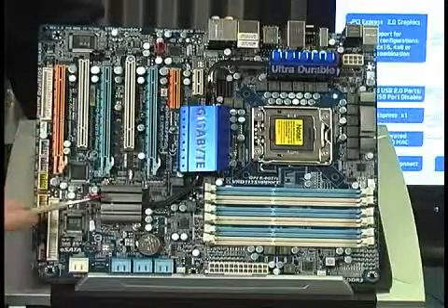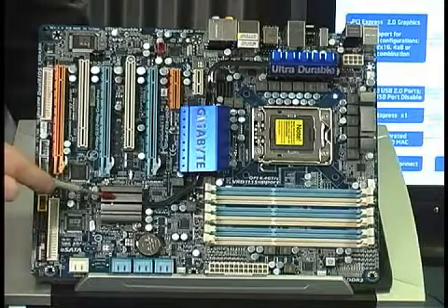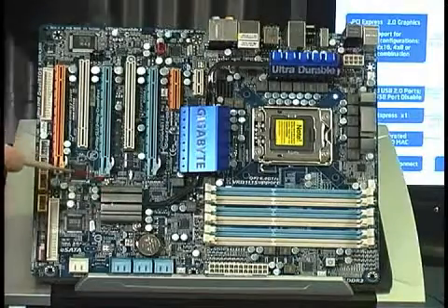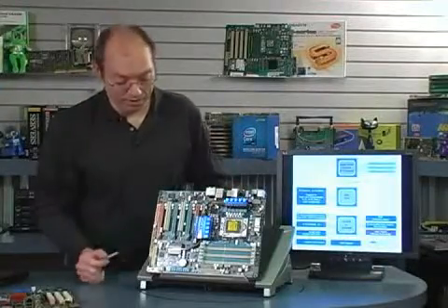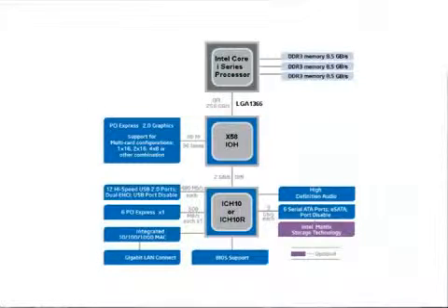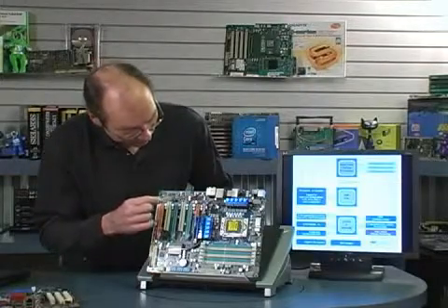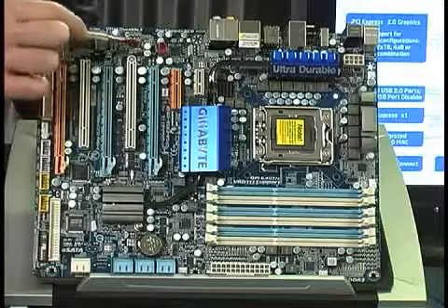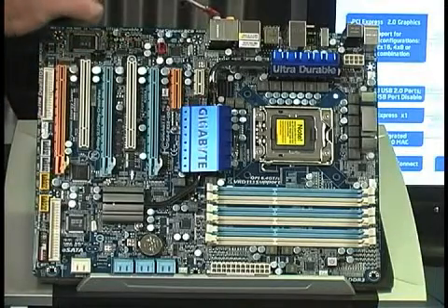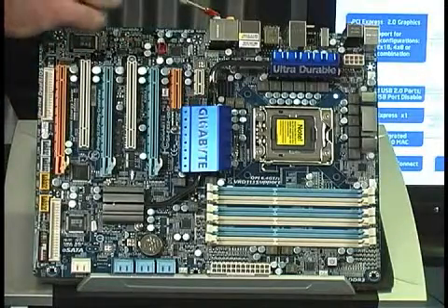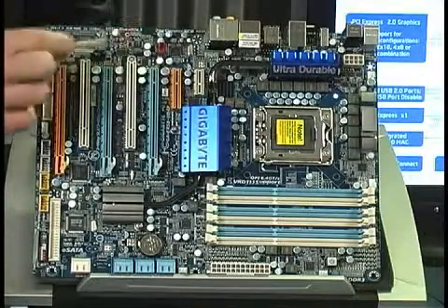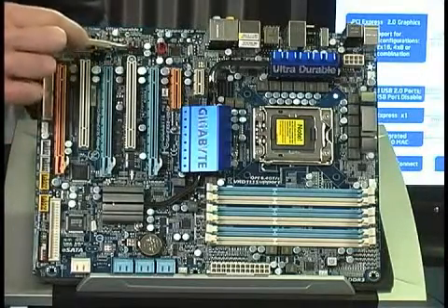Now, let's look at the Southbridge. The Southbridge is a very much, how should I say, overworked or in-demand chip in a modern system. As you can see, look at all of the interconnects to the Southbridge. For example, in this we have the audio. And on this motherboard, we have an audio chip, which is actually located right here. So this chip right here provides a connection to the audio jacks on the back where you can plug in speakers. This one happens to support 7.1 audio, and this happens to be a Realtek audio chip.